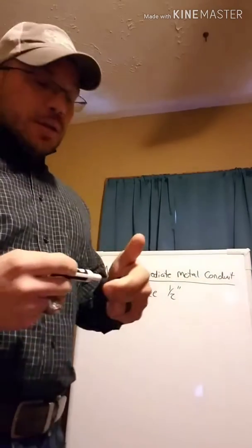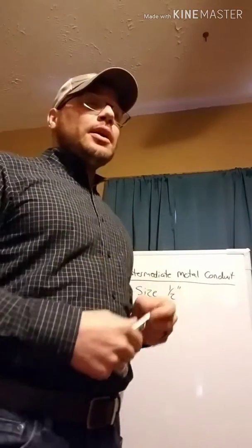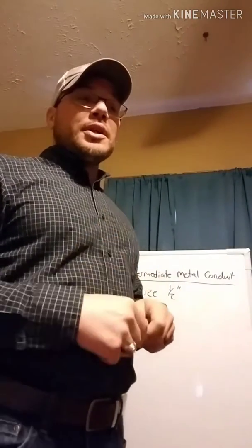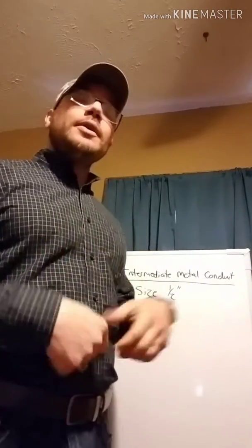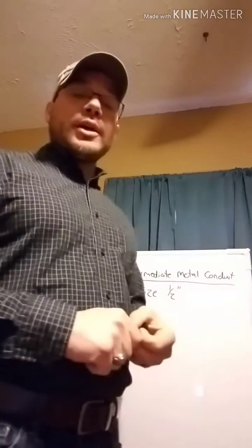Okay, and that's just like EMT or most of the other things. Besides if we're using it to connect motor leads on the motor itself, we're going to use 1/2 inch as smallest. 3/8 of course can be used, I guess, for the motor leads.